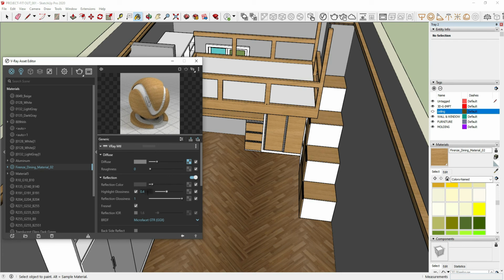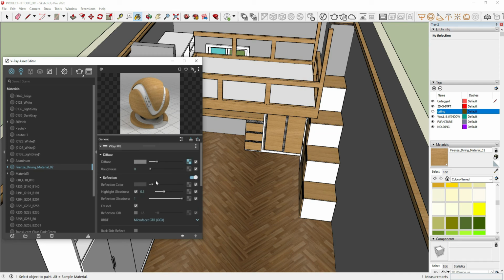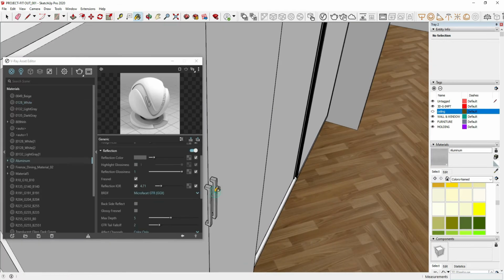Now, you can edit the desired settings like reflection, refraction, opacity, and others. Here, I usually select the reflection, just adding to the reflection color and the glossiness by moving the point in the right direction. I do this in all of the components except for the lightings, which have a different setting.